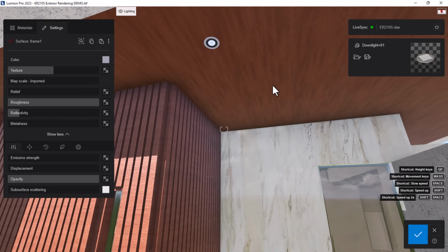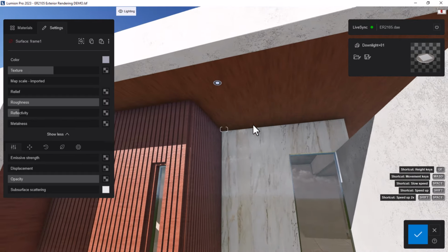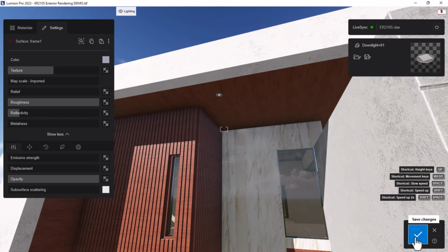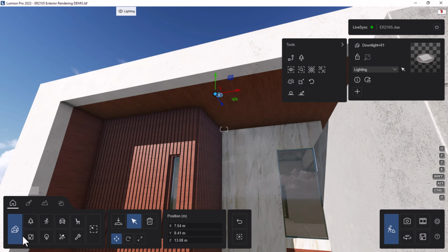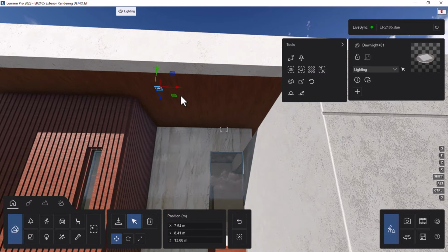What I need to do now is to duplicate it along there. I'm going to save changes, then go back to content library so that I can activate the editing of this element. So I'm going to copy this on the x-axis, right? By holding Alt, like I said, I'm going to move it somewhere to there.